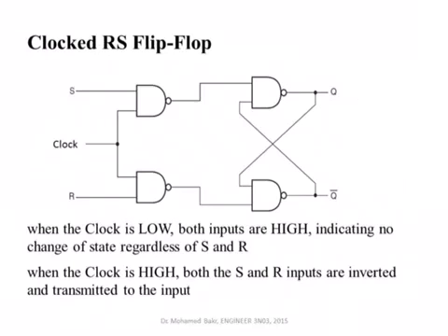Of course, the problem with an RS flip-flop is that in many applications I would like to get the memory set or reset, or to load new data into registers, only with a clock, with a computer clock. And this is what we have in all our devices. There is some clock that determines the order of execution of commands in the microprocessor, inside our cell phones or inside our computers and so on. So this is one way of doing this.